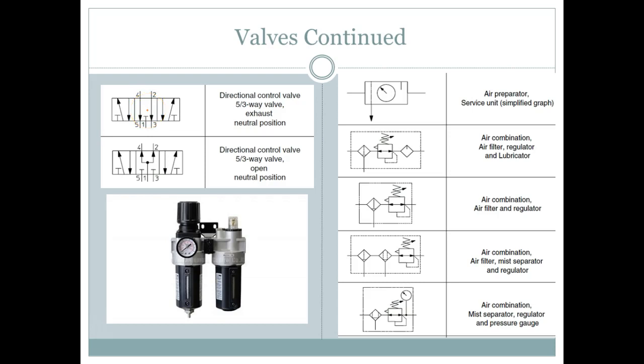Now on pneumatics, we're not going to ever vent the compressor. Because in fluid power, on liquid, you create pressure as soon as you want to use it. If I'm using pneumatics, what do we have to do first? We have to compress it. So in my experience, you'll never see a vented center where the pressure is vented. You always block it off if we're not using it.